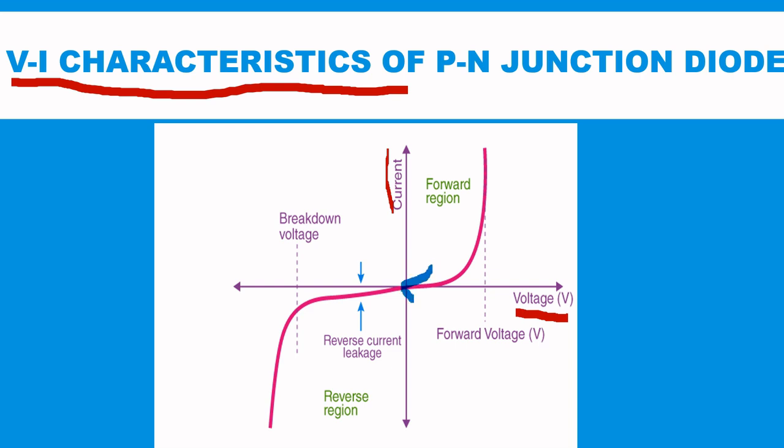When the diode is in forward bias, the current increases slowly and the curve obtained is non-linear as the voltage applied to the diode overcomes the potential barrier. Once the diode overcomes the potential barrier, the diode behaves normally and the curve rises sharply as external voltage increases. The curve obtained is linear.